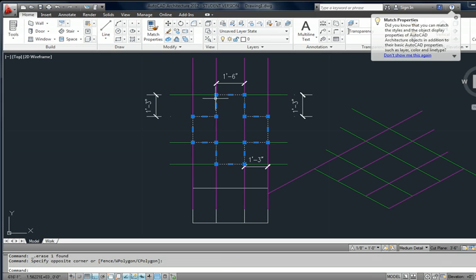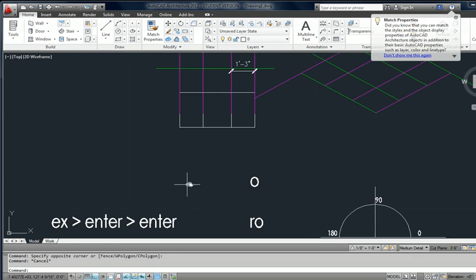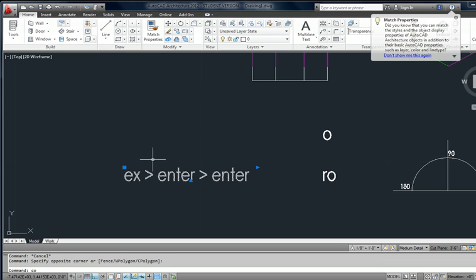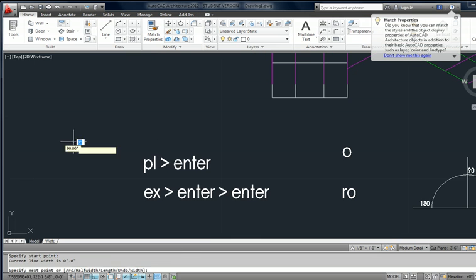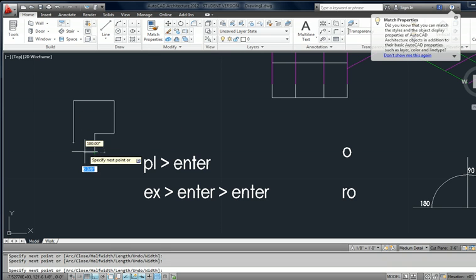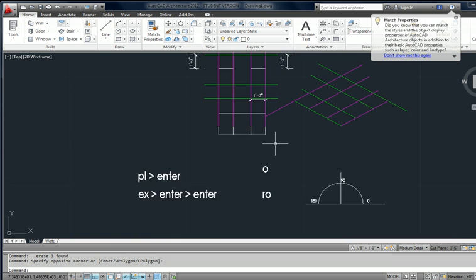Okay? I can look at where the cross is intersecting each connective point, the green and the magenta. I can just simply use the command called polyline. Polyline, again, remember, will allow us to create multiple lines. This is a polyline. Notice how all the lines are connecting. Okay, if I touch one line segment, they all get selected. So I'm going to use the polyline command.